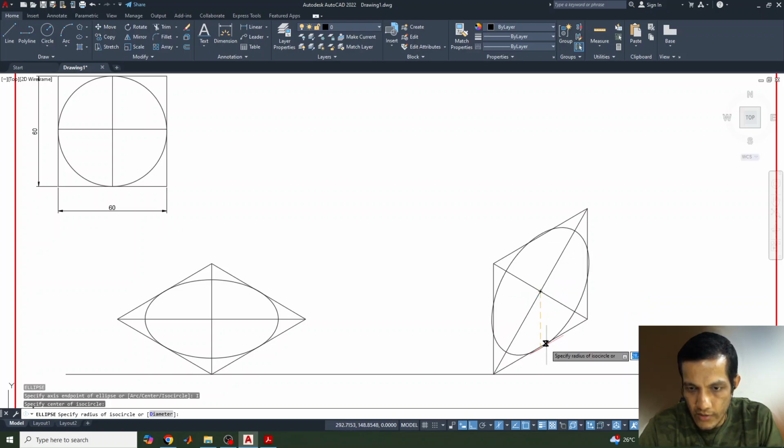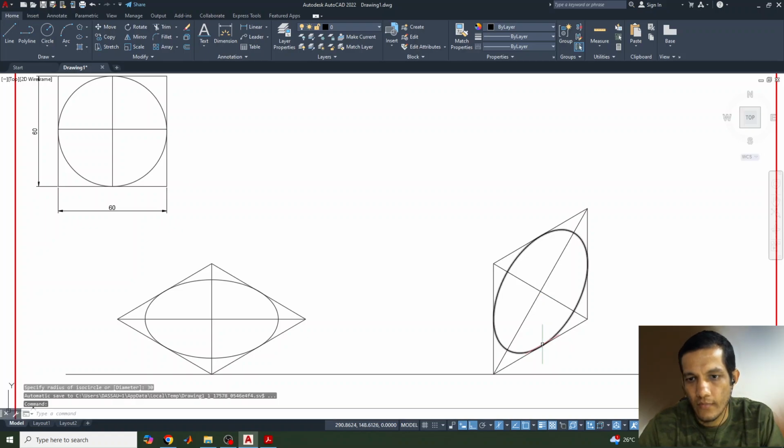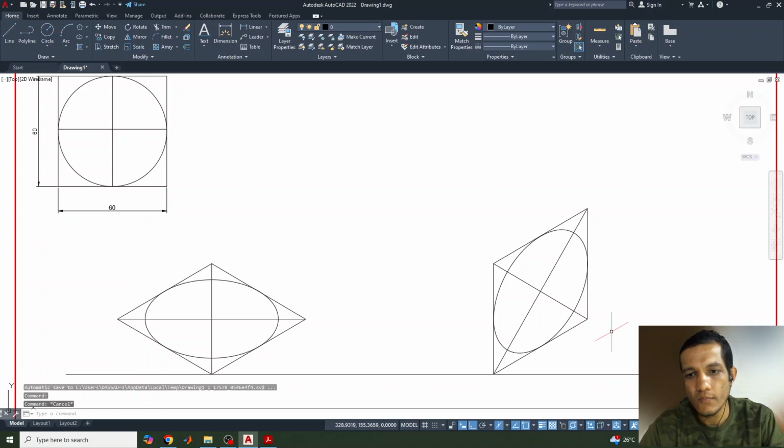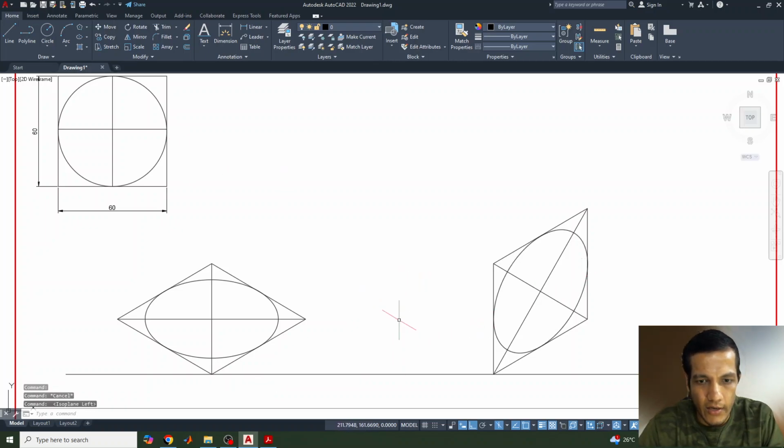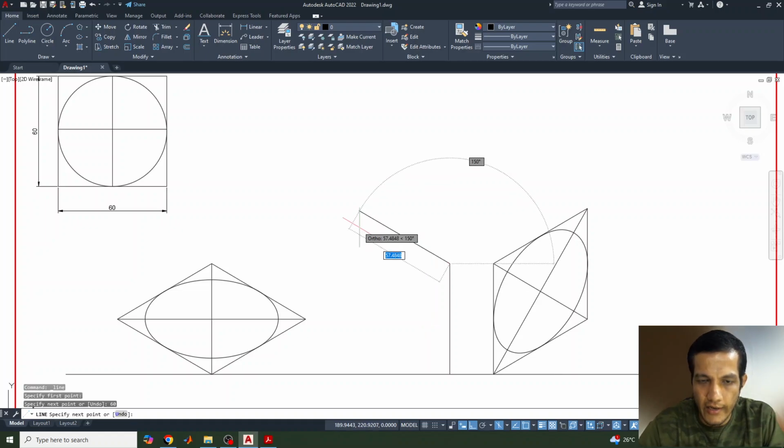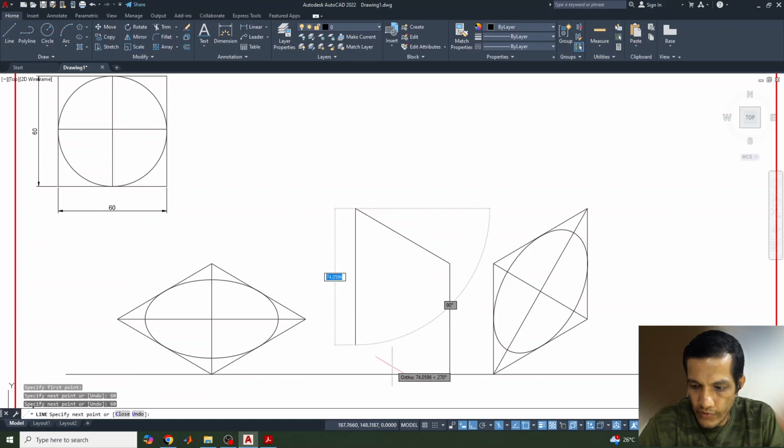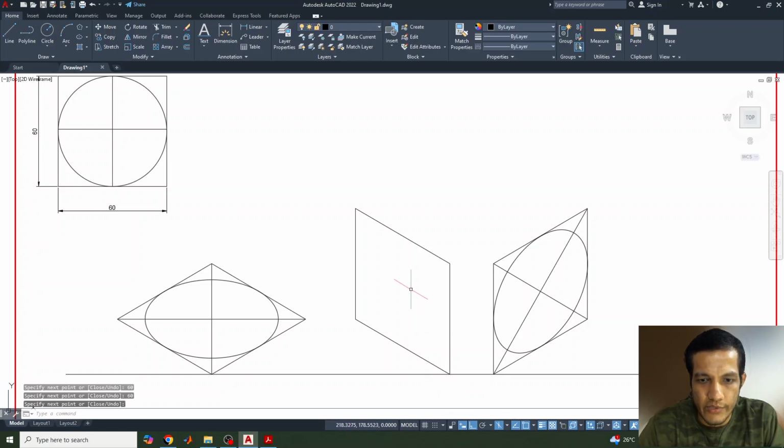Now you can select on this nearest point, or you can go for 30. Now this is the ISO right side circle. Similarly, again I will click F5. Now the cursor changed to ISO left. Again we can select this line, go for 60 height, again width is 60, again length 60, and it will be back to 60 here. Okay, so I'm going to close it.